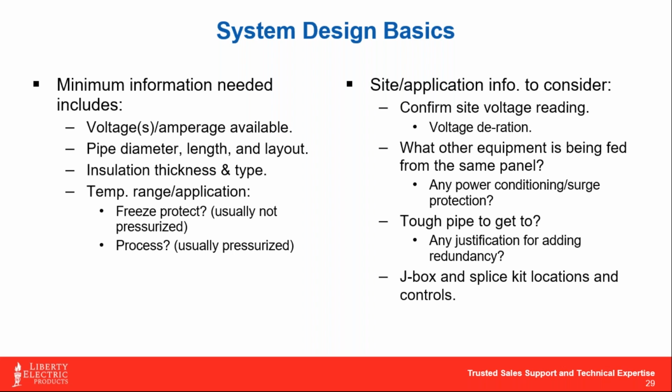So if we're engineering a job at 208 volt, and we know already that we're going to be handicapped, you could say, a little bit on that one, and then come to find out you're really only pulling 202 or 203 on that circuit, not 208, you've got to compensate a little bit for that too. So that's why we try to dot that I, cross that T.